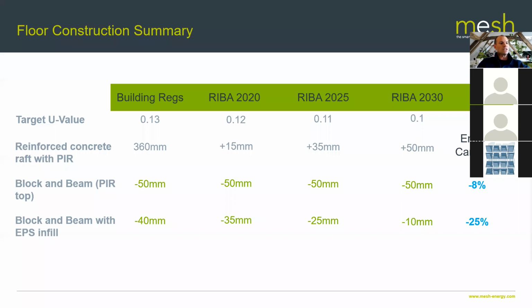And I would strongly suggest that anybody takes a look at GGBS concrete, which stands for ground granulated blast furnace slag concrete. So essentially that's a recycled product. Slag is obviously a byproduct of manufacturing processes, and using that in there as the aggregate makes a big difference in the embodied carbon in concrete footings.